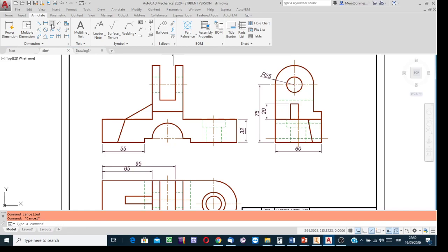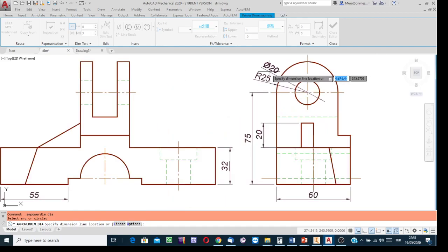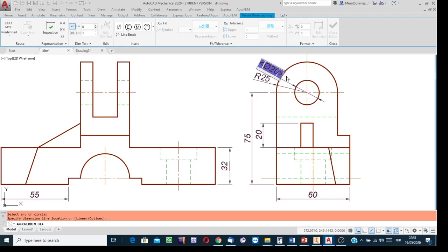Well, for this drill I'm going to use the dimensioning technique. Click on the diameter button or power dimension, press enter and indicate the circle. Well, since this is a crowded region, may show it over here, but if the space is sufficiently large to show this dimension without any clash, show it preferably between the views. You know the reason, because the z-axis is commonly used.